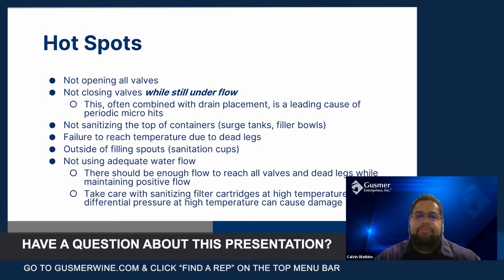It's tough to see whether every square centimeter of the winery is getting the proper sanitation fluid to that spot. You have a lot of piping in there, so it's not uncommon to have dead legs. We have to deal with those, but we want to do our best to make sure that our dead legs get the proper sanitation fluid and that they get up to temperature.